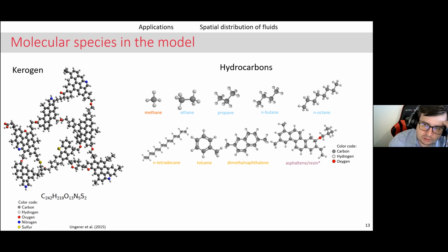A quick question from me. In the tight reservoir, it seems that what we take as a bottom hole sample, and which I, with my limited production engineering mindset, would probably put into every single simulator as representative of the fluid, might not actually be the fluid of the reservoir. Could similar problems be present in non-tight, higher Darcy sands or reservoirs? That what we would take at the bottom hole would not be representative of the reservoir itself.